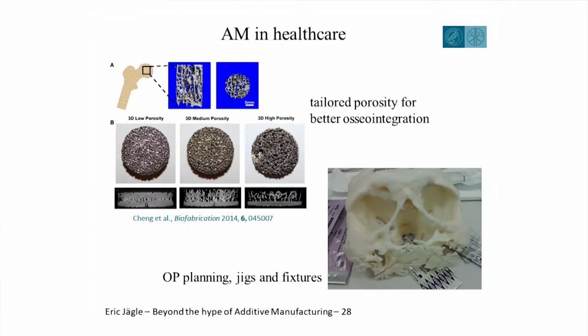The attractive feature for these orthopedic implants is the porous surface. So depending on the process, you can deliberately make the surface very porous, and this helps in osseointegration, so bone ingrowth into the implant that you're getting.